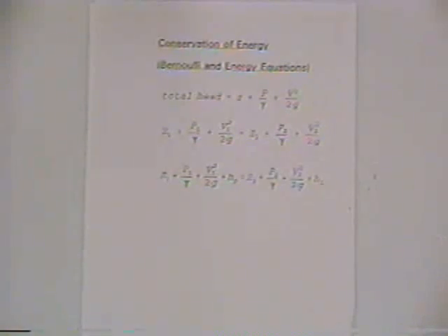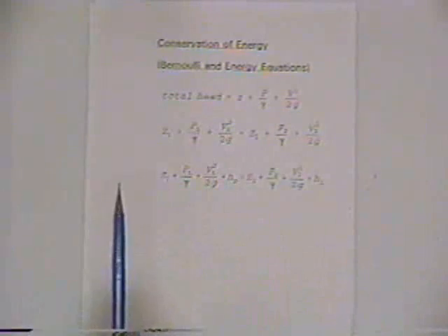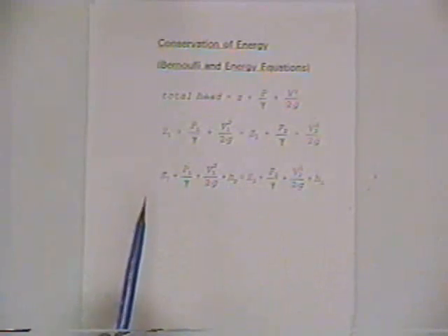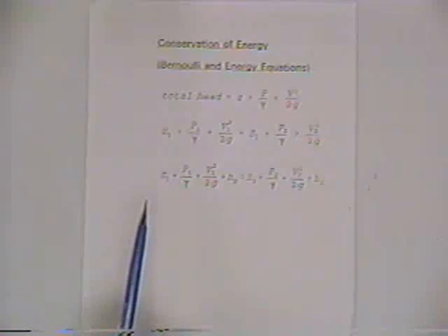And so we went to the basic derivation of the Euler equation. We would derive energy per unit mass, and then we'd divide by g, and we'd get energy per unit weight. And so that's convenient to work with, because if you've got energy in, say, Newton meters per unit weight, Newton meters per Newton, that gives you head in meters, which is quite convenient.